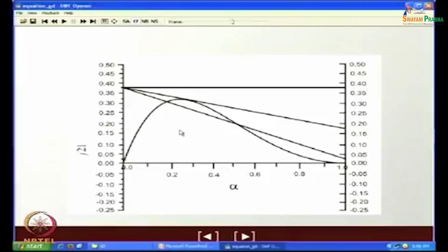So, what do you get under these particular situations? From these situations, we find that below a critical value of alpha, you have 2 points of intersection. That means, for counter current flow with gas up, liquid down, there can be two possible flow patterns where the flow can be stable.